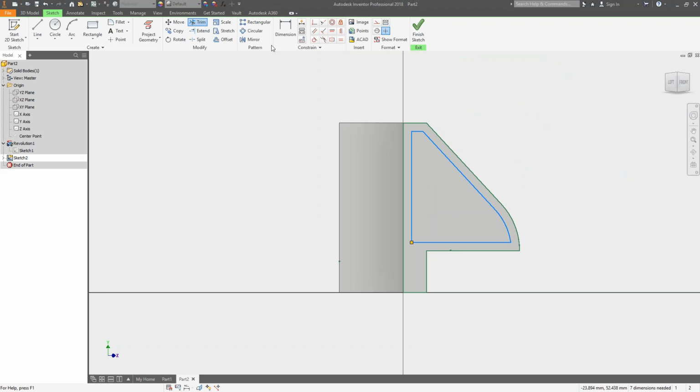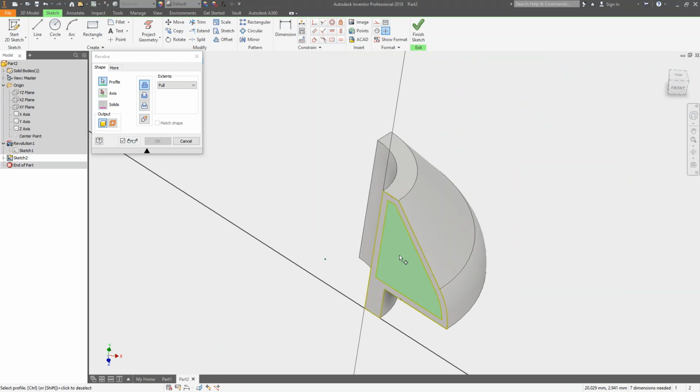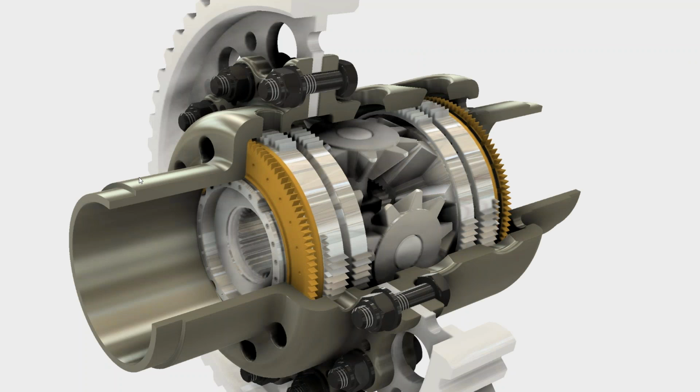So what I can do now is I can issue my revolve, but it doesn't pick up the axis. So what I have to do is choose axis, and because I built this on 0, 0, I can actually choose one of the origin axes. This is another good way to keep your sketches and your geometry pretty clean. I didn't have to edit or add additional geometry, so I will add in, whoop, there we go.